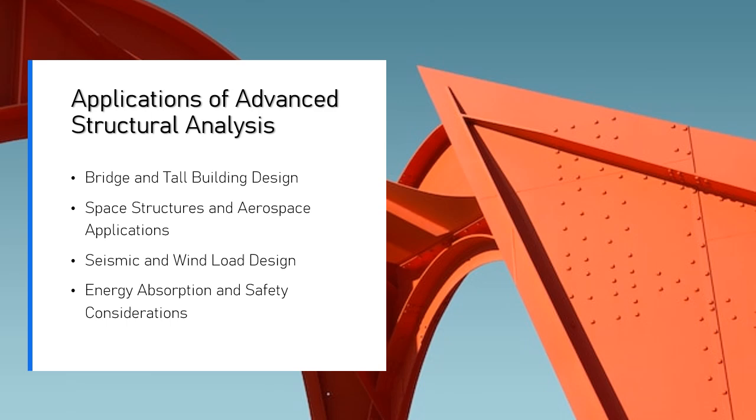2. Seismic design code compliance. In addition to advanced analysis, building codes provide guidelines on how to design for seismic forces. For instance, in the U.S., the International Building Code, IBC, and the ASCE 7 standards specify minimum seismic design requirements based on the building's location, size, and importance.